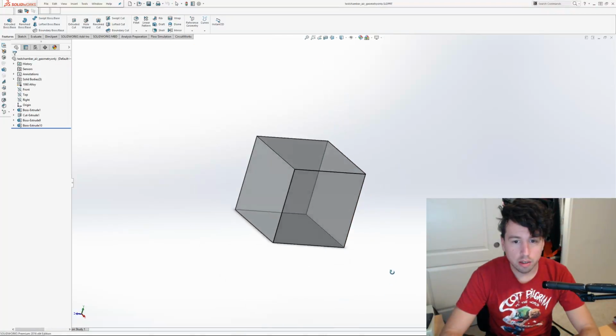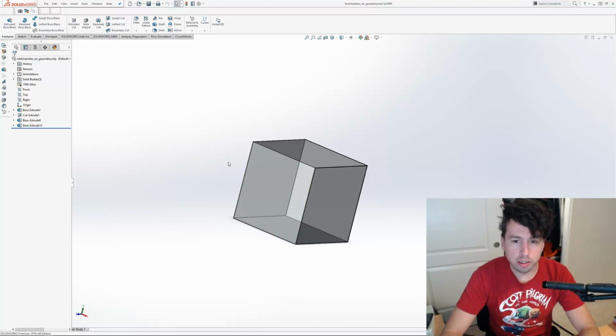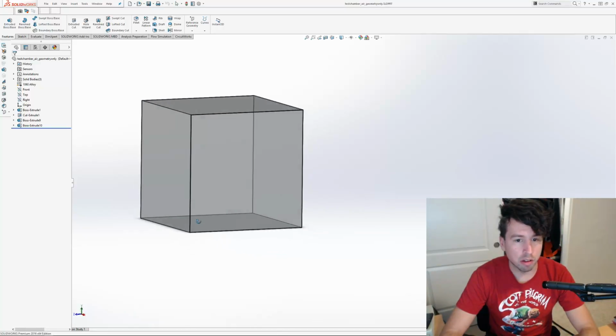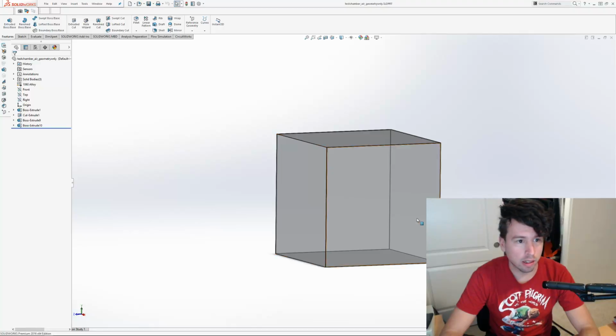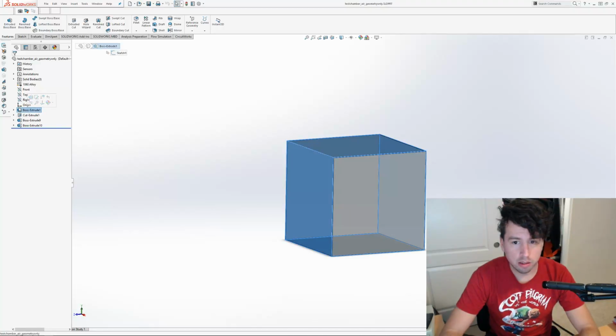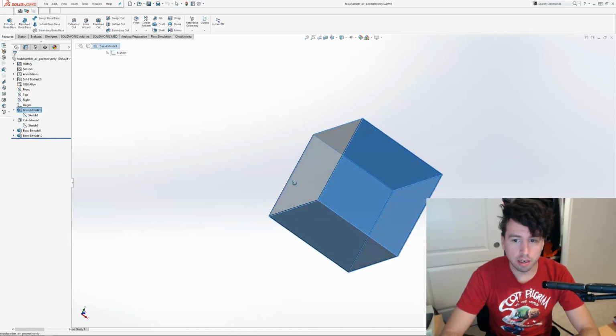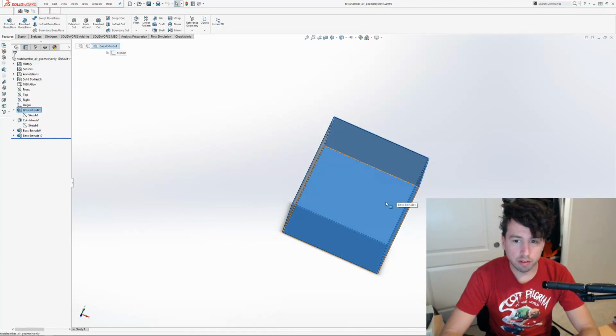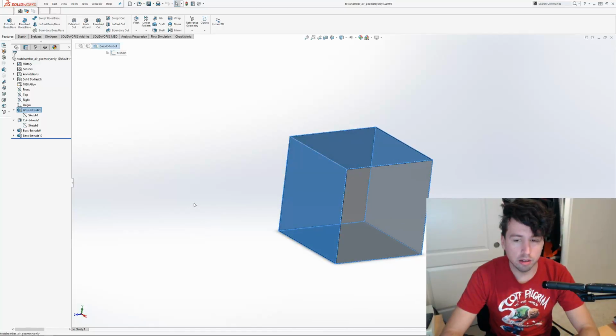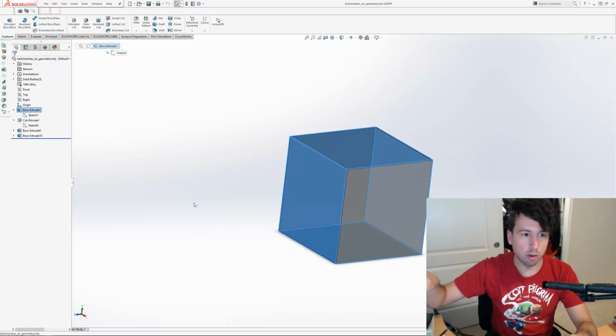Geometry only. So I made this out of aluminum. All my bodies are made out of aluminum, which, if you want to do any sort of material study, you can. I just made it out of aluminum because that's what we have on campus. So my first box is just a 700 by 700 millimeter volume. I cut a 695 by 695 square through the body, so I would have 5 millimeters on each side, which gives me a box with 2 holes in it, so you can imagine air flowing through it.